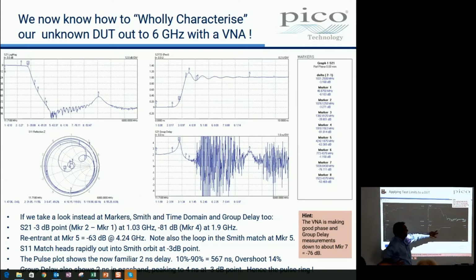And you can see I just unscrewed one of the connectors slightly on the output, and the VSWR's gone all out, and the limits test has now functioned, and it's finding a failure against limit test. So this was the idea of the test. You can show that limits test can be applied and how it works, and you simply have to just loosen a connector and you'll see it all move. Which is of course a warning against not tightening connectors properly in the first place.